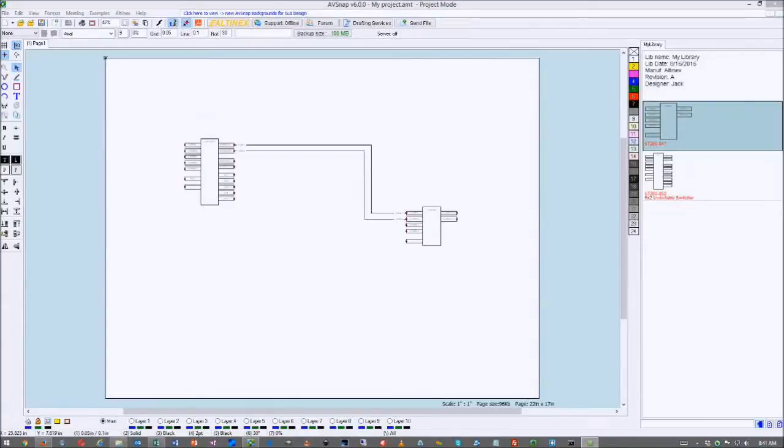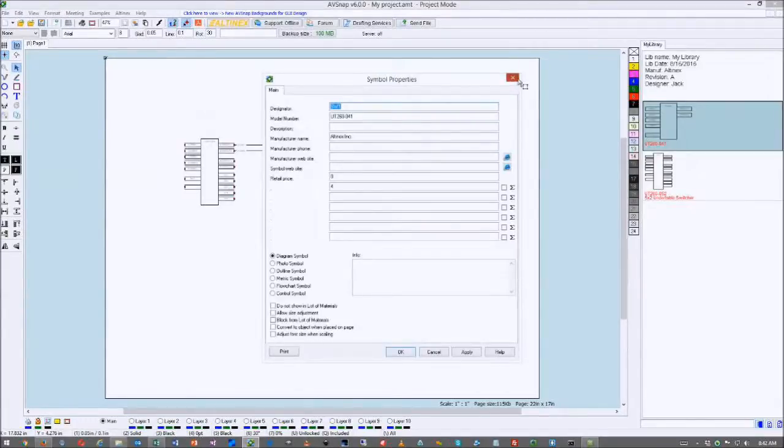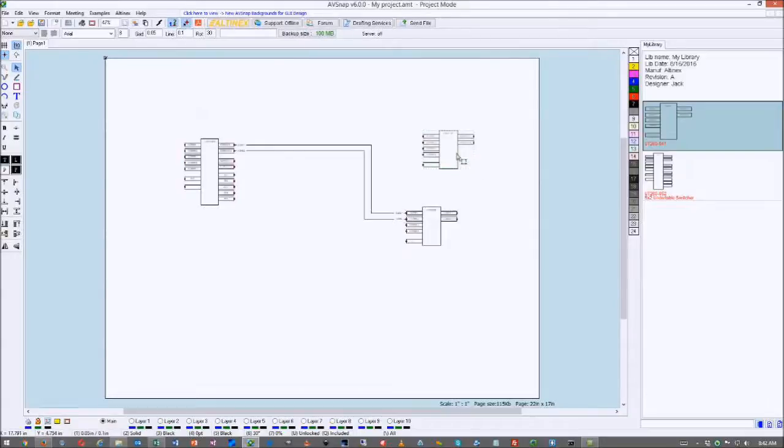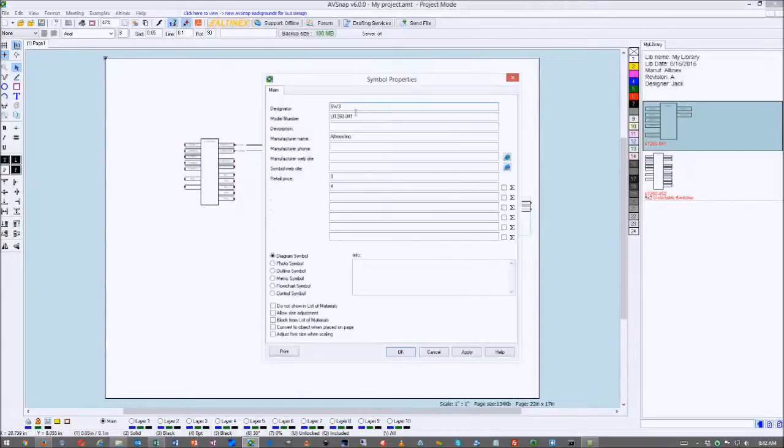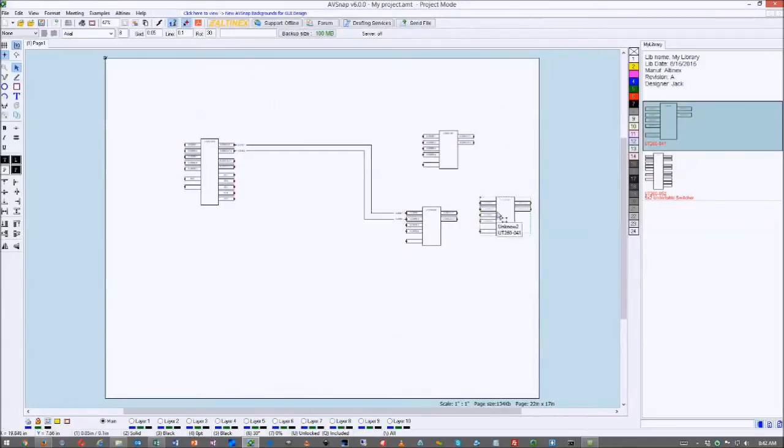So let me look at the other questions that we may have here. If I want to have the same designator SW2 appear on multiple pages, video and control, can you just copy paste the same symbol and maintain the designator? By default, when you copy the symbol, the designator will automatically increase. If you need to maintain it, the only way to do it at this point is to actually go in and physically modify it to be the same. It's okay for us to have multiple symbols of the same designator, but once you move it to a second page, you might have to manually do this.